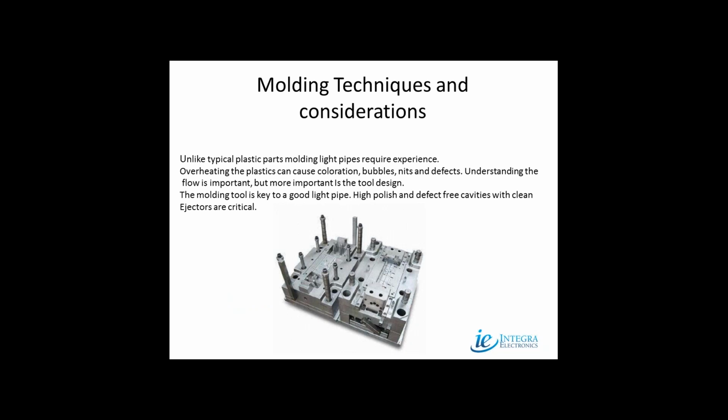So we talked a little bit about designing the light pipes and just a very high-level overview of the designing process. Let's talk a little bit about the molding techniques and considerations. This is almost equally as important as the light pipe design itself. Finding a good molder that can develop a tool that will be defect-free and provide the right type of extraction with minimal sinkage of the parts is absolutely critical.